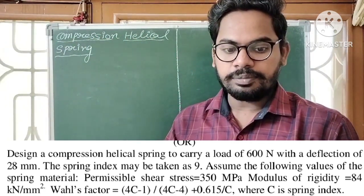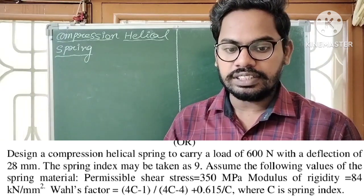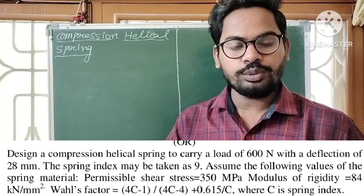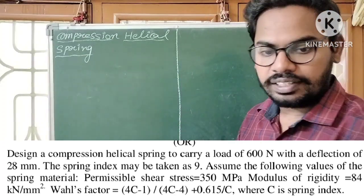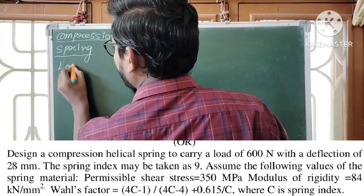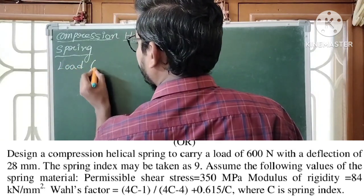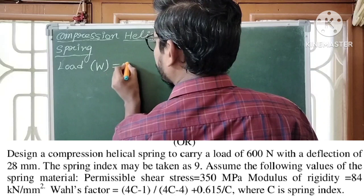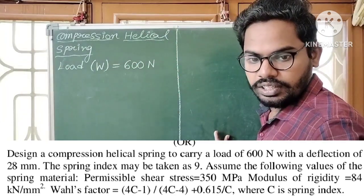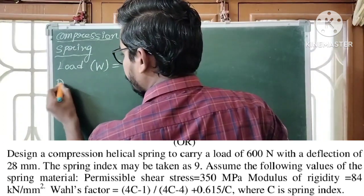Here, a compression helical spring is to carry a load of 600 Newton. So the helical spring is subjected to an axial load. First of all, note down the given data. Load W is equal to 600 Newton, and deflection given.